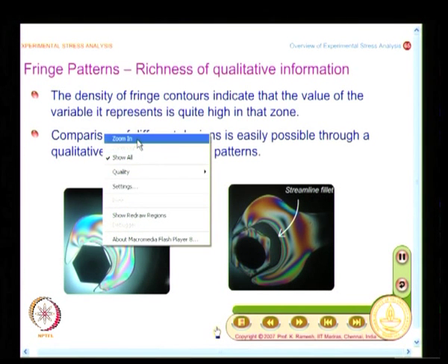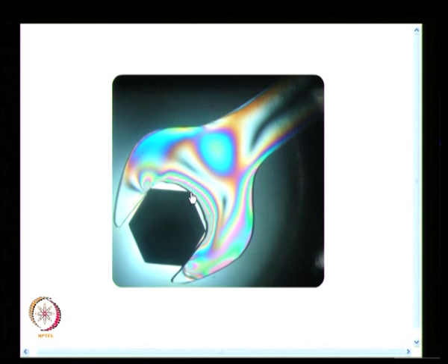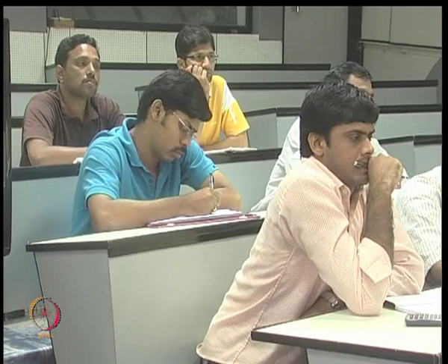So, you know how a fillet is made. Suppose I go to any machining process, it is easier to make a circular fillet, because the machining operation is simple. I can go and make a circular fillet, and why do I make a fillet? I would like to minimize the sharp geometric changes, and I would like to have a smooth variation, and this smooth variation you could do by a fillet. So, you essentially reduce the stress concentration.